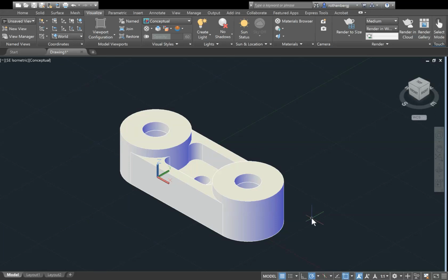Hello everyone and welcome to video 3 of 3 of how to construct the 3D saddle block broken out sectional. In this video, I will be using the fillet command to smooth out all of the edges on this piece, and then I will be removing part of one of the corners to actually make it the broken out sectional.